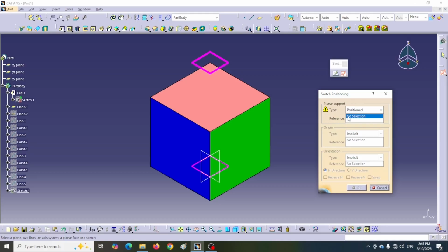But from here on, we specify the coordinate center plane and the coordinate axis on the selected plane. I select a plane called plane 2 that is parallel to the green surface. You see that the name of this plane is written in the box in front of the reference option. This plane will be our drawing plane in the Sketch environment.